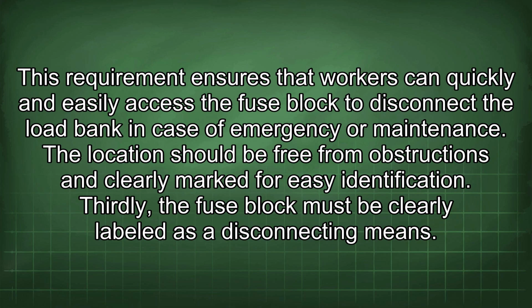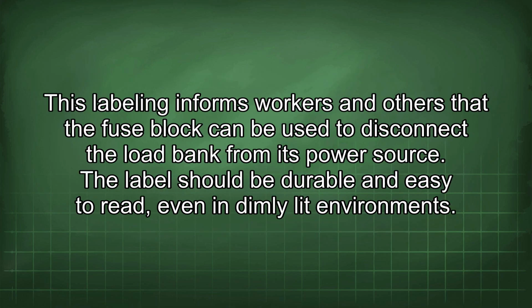Thirdly, the fuse block must be clearly labeled as a disconnecting means. This labeling informs workers and others that the fuse block can be used to disconnect the load bank from its power source. The label should be durable and easy to read even in dimly lit environments.